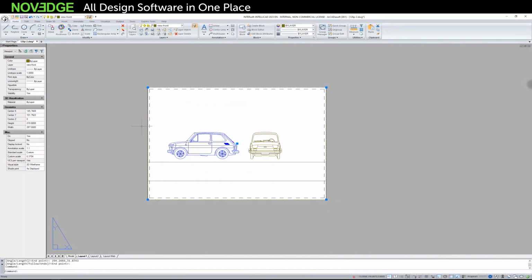I select the viewport, so the frame that defines what you are printing, what is in the scope of the printing. And in addition to its size, here in this geometry section, you have a scale. Now it's a user scale, and you can choose at what scale you want to print. Now, what I had there in the model, when I wanted to print in a scale of 1 to 50, I chose a scale of 1 to 5, because again, I converted the unit from centimeters to millimeters, and here I do exactly the same.